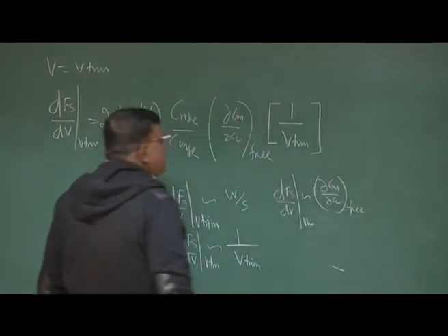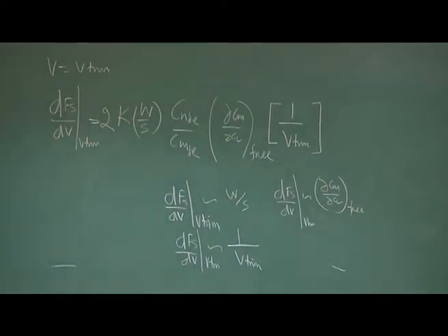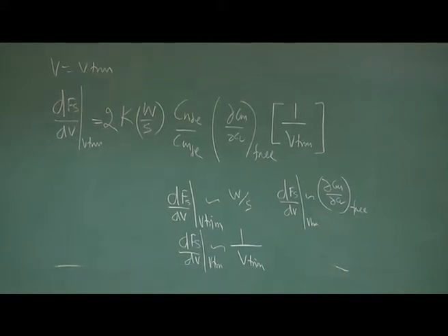So you could see that if I take CG forward, then dFs by dV, the slope, gradient will increase. More stick free stable, more the dFs by dV. Okay? So these are the understanding from this expression.